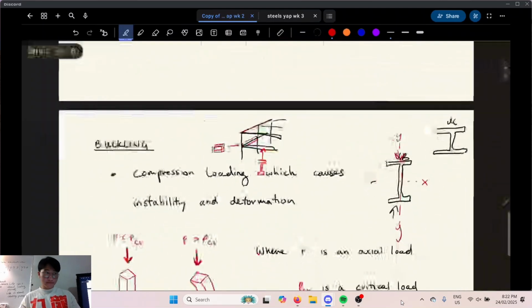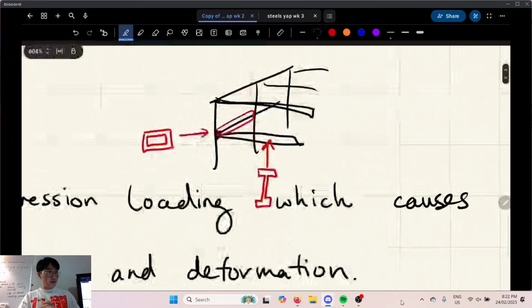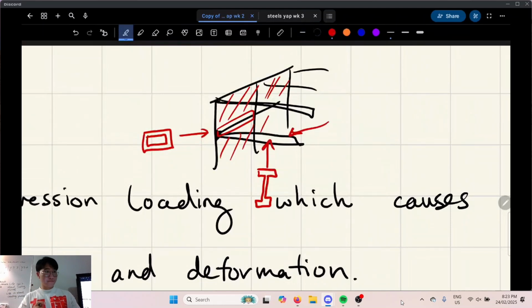But can't wind come from any direction? It's shielded, so there's glass and facades out here. So the beams are protected from the wind essentially, because they're supporting the majority of the building, but they don't really take the sideways loading.